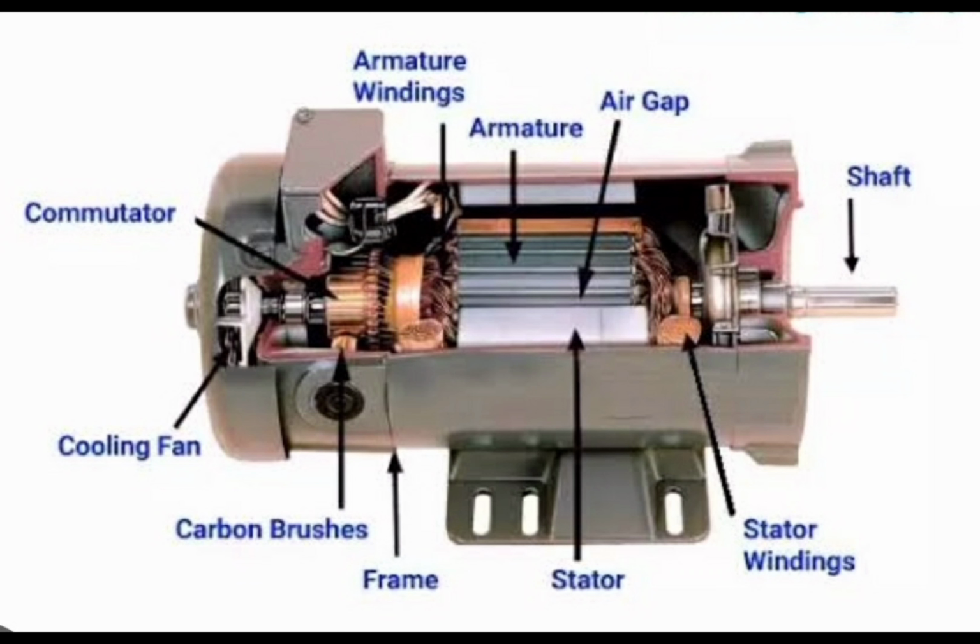Next one, the slot or teeth. The non-conducting slot liners are frequently jammed between the slot walls as well as coils for safety from scratches, mechanical support and additional electrical insulation. The magnetic material between the slots is called teeth. Next one is the motor housing. The housing of the motor gives support to the brushes, bearings and the iron core.